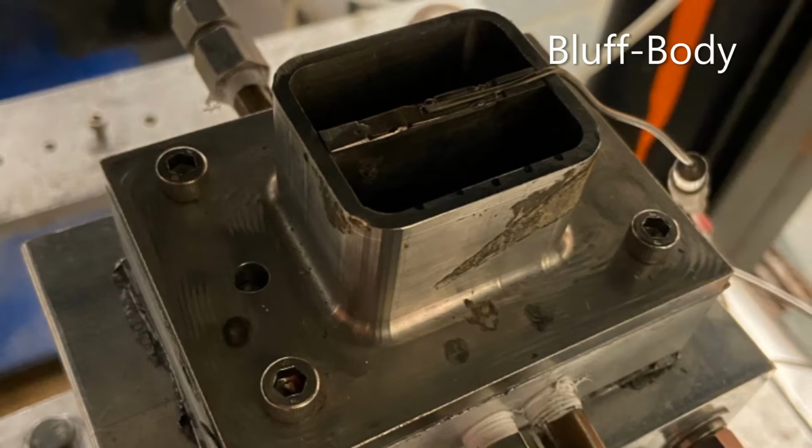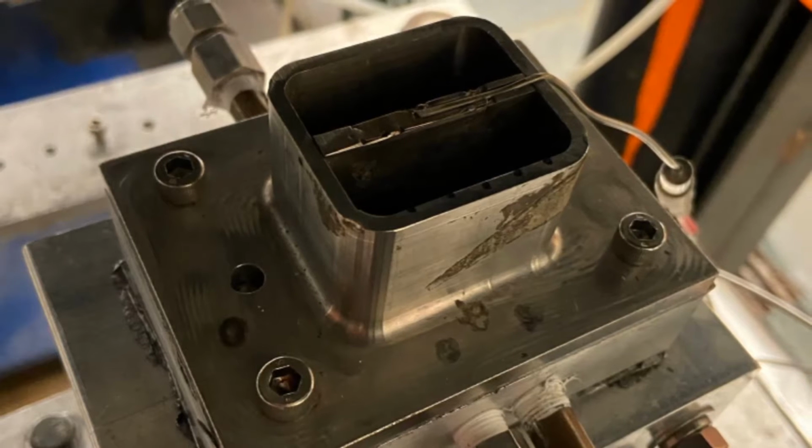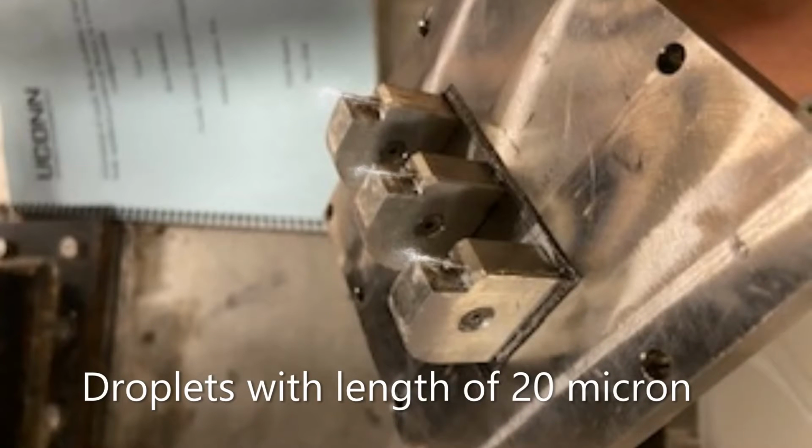This rig's flame is stabilized on the bluff body, which is the rectangular piece spanning across the cross-section, parallel to the long side of the rig exit. I am investigating pre-mixed flames, which means mixing the fuel with air before combustion. For optimal premixing, I am vaporizing the liquid fuel using an atomizer that shoots fuel droplets of about 20 micron in length into a heated airstream.